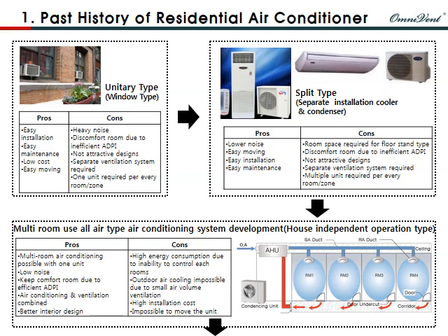The upper right image shows the advanced split air conditioner, which prevents heavy indoor condenser noise. However, these units take over interior space and still leave an unattractive appearance. The biggest disadvantage is that it requires additional refrigerant and drain piping work. This type of AC unit has a low ADPI, requires a separate ventilation system, and each room requires its own air conditioner.